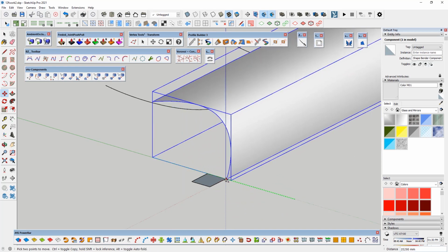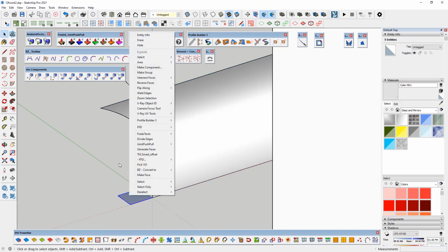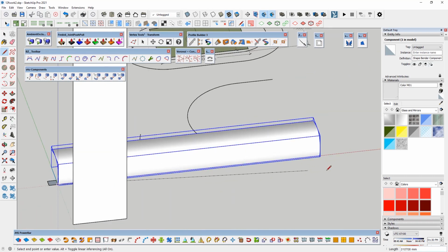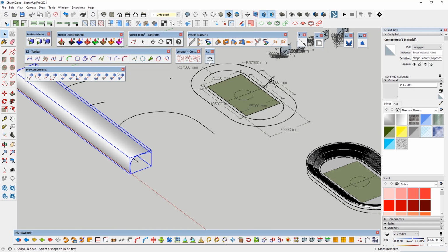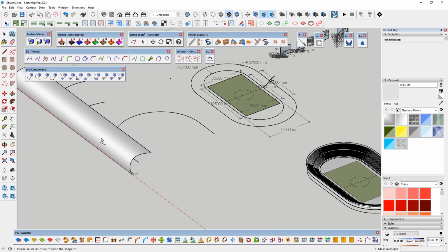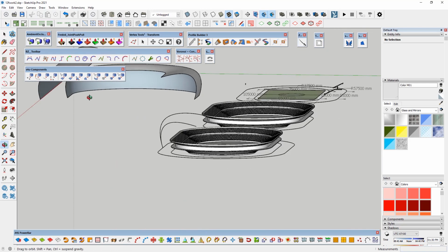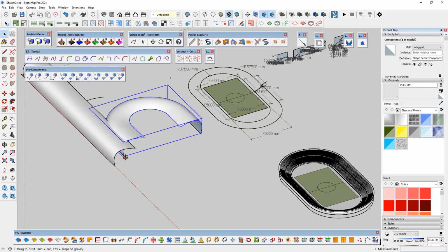and after that I will just move it with the keyboard, and I will try to snap it to the 0.0 axis. Okay, then we can remove the square, and we need to draw the line on the red axis. Always remember to do it on the red axis with the lock, using your arrow on the keyboard. And after that we are ready to convert it from the straight to the bend. Check if the end and start point is correct, and we have one of the top construction.